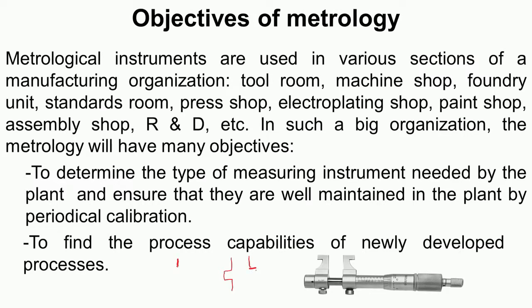I am just writing the sketch. So there is a workpiece with an internal groove like this. Then the quality control department should suggest an appropriate instrument. So in places like this, one can use an inside micrometer caliper of this type, and also sometimes we may